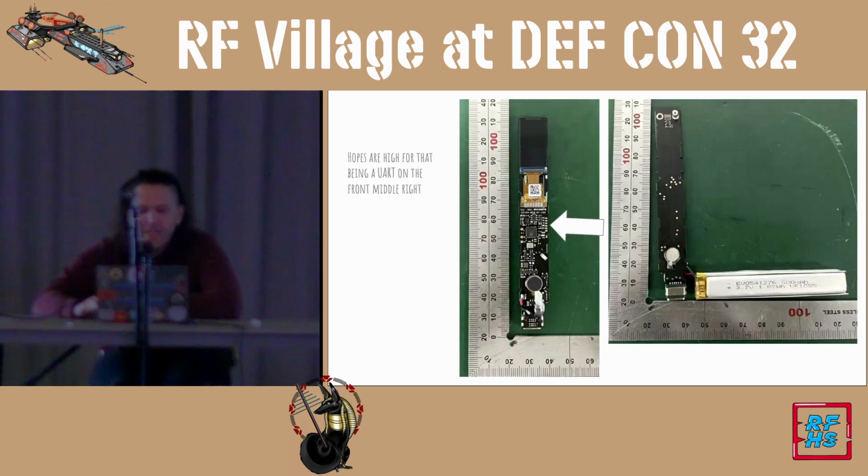The reason why is because they upload photos of the internal circuit boards as part of the FCC certification process. If you've got something's FCC ID, or if you know who the manufacturer of that device is, you can plop that in there, and you get some beautiful photos of stuff. You don't even have to buy it, so you can figure out what is in a thing before you even spend any money on it.